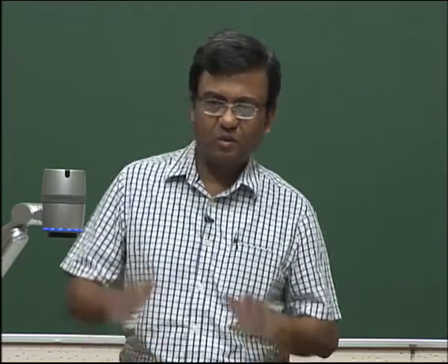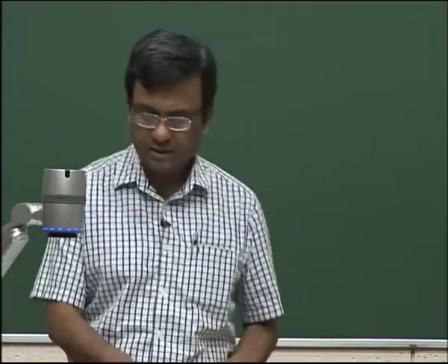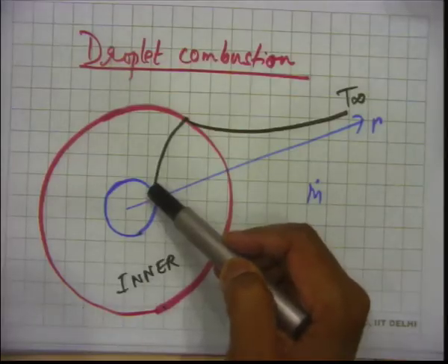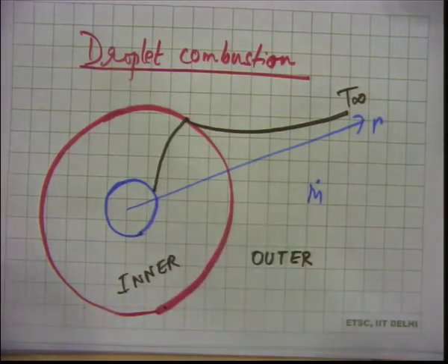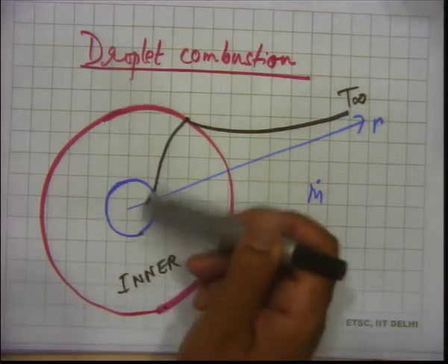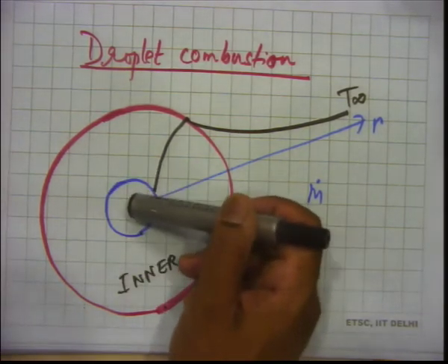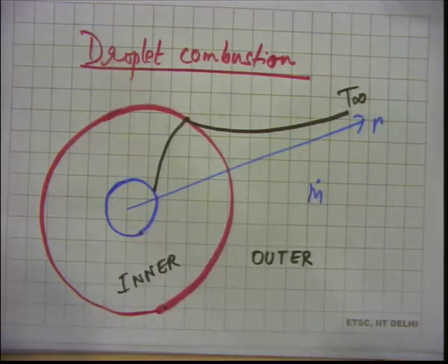So it's going to be more involved. But if you can get this temperature profile, then we can again do dT/dr at r equal to rs, multiply it by thermal conductivity, okay, and the area of the droplet to know how much heat is going into the droplet, and then thereby relate that to the evaporation rate of the droplet.